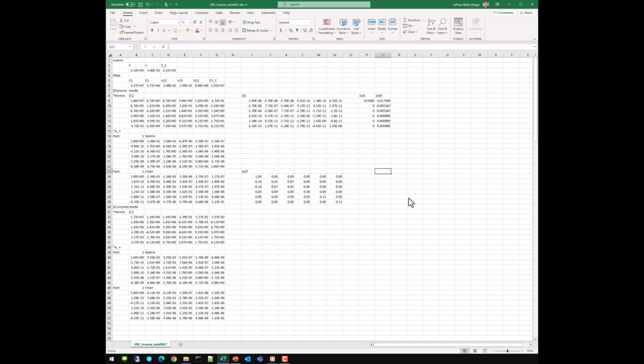Now, how do I get the strain of the 0 degree specimen in the fiber? Well, easy enough. All I have to do is multiply my amplification matrix by my homogenized strains. And I will get the strains now in the fiber. Okay, and so you can see, where I had 17,300 microstrain, I still have the same 17,300 microstrain because I have a 1, 0, 0, 0, which will always happen. But the other strains will not be exactly the same.